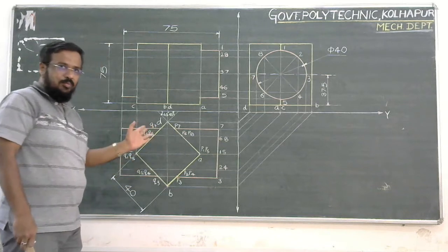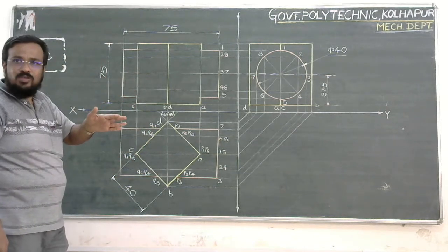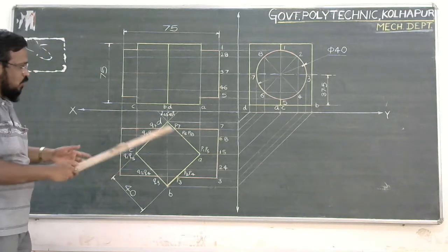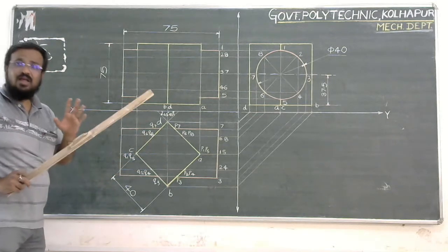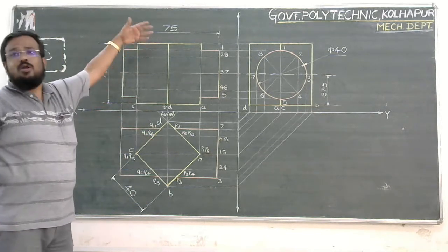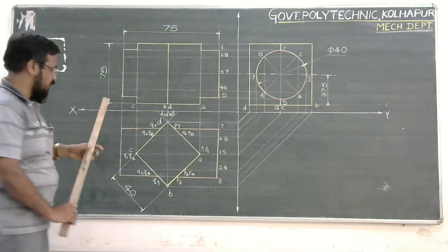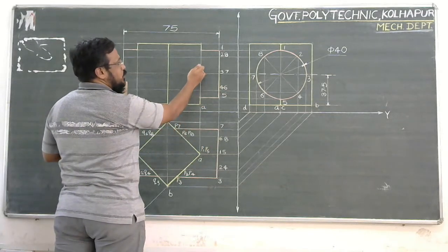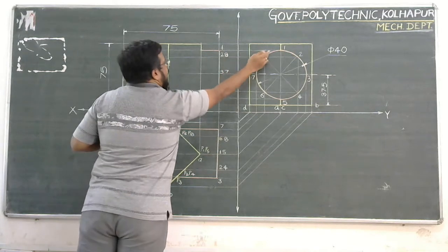One cutting points you will get on the front side of this object also, as well as on the back side. So all our points are being located over here. Remember, these are the intersecting surfaces' points. Now we need to transfer all these points into the front view. Okay. So this P1, vertically up projector, and one transferred from horizontal.